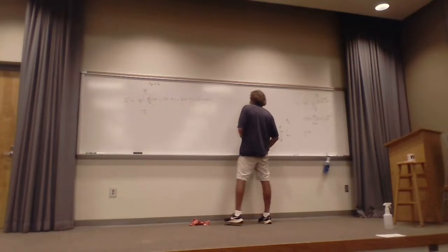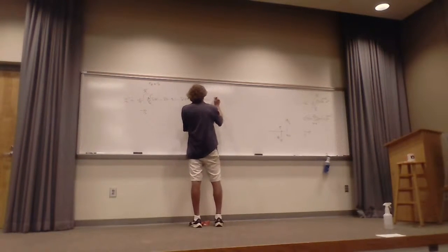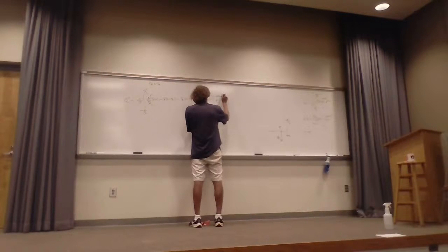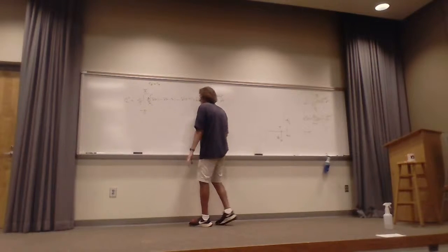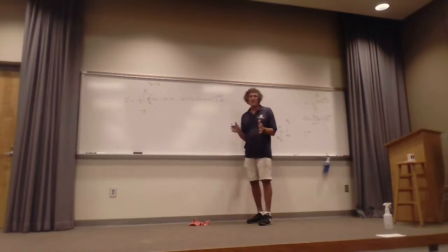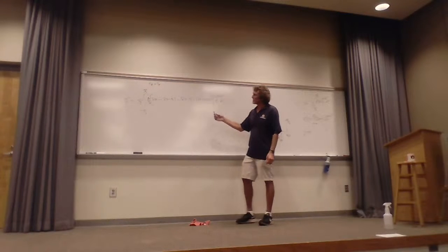Then, when all is said and done, this has to be multiplied by e to the minus j n omega naught t dt. Okay, now here's why I'm doing that. For a regular trapezoidal wave like this, it's really something that's got a rise time and fall time. To do the Fourier series coefficients with integration by parts is a pain. This is trivial. Why is it trivial?